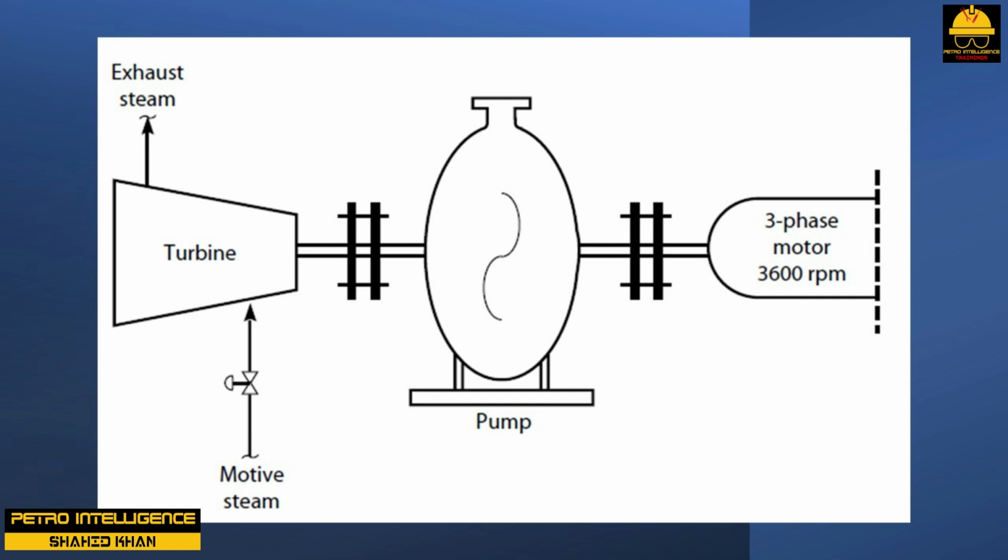While the turbine will produce shaft work, and will help the motor spin, the pump speed will remain unchanged. The extra shaft work from the turbine will just reduce the shaft work required from the motor shown in picture. The amperage load on the motor will just be reduced.